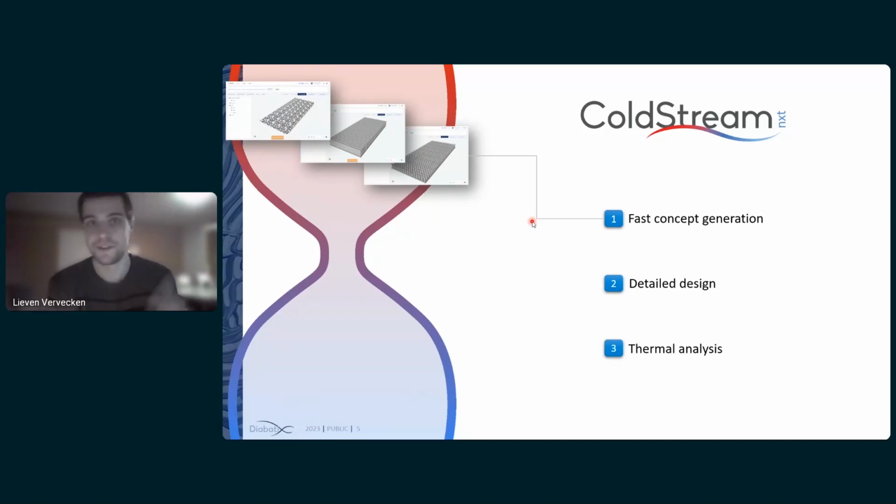If you want to know more about it, feel free to rewatch one of our previous webinars. The fast concept generation phase, as the word says, can quickly generate a bunch of different designs, giving you insights into how a change in design affects the performance. For example, if the pin fins, which can be die cast, perform much worse compared to TPMS structures, which are exclusive to 3D printing, you basically have to go with 3D printing if your thermal requirements are very, very strict.